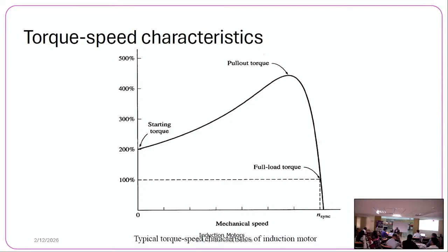Actually I have a doubt in this speed control of induction motor. One method is there in which the rotor can inject a voltage and control the speed. In that method, can you run the motor at synchronous speed also? Yes, definitely. We cannot say that the induction motor will not run at synchronous speed. It can run at synchronous speed, but it cannot go beyond synchronous speed by the other method. Time permitting, either today or tomorrow we will discuss it, maybe at the end.